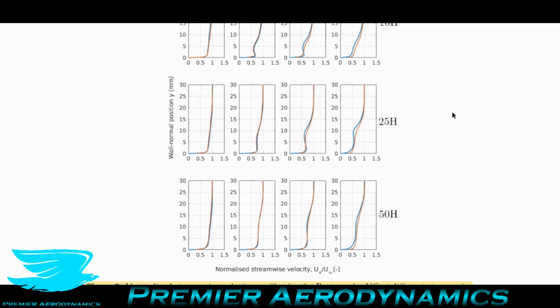And why is that? Well, that's because the vortices are now dissipating, they're growing, and they're getting weaker in their core, lower vorticity in their core, I should say, they are breaking down, which then leads to their weakness. But because they are getting bigger, they're interacting with a lot more fluid to the side of them. Of the vortex generator, they're covering more distance. So that means that between the vortex generators now, that boundary layer is getting more affected the further downstream you go, until the vortices break down, of course.